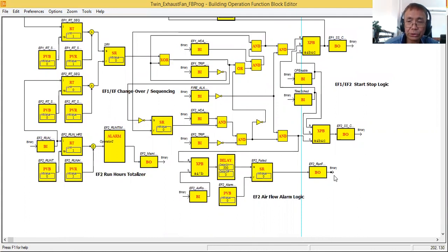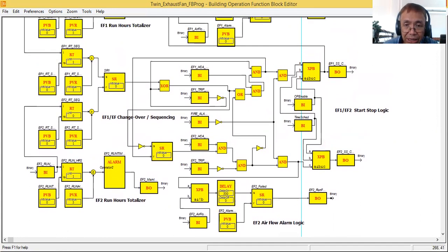So you will have three small programs that are easy to understand because they are small and manageable. But if you have a big logic, sometimes you feel you cannot follow the logic. So it's good advice to break your big and complicated control logic into smaller control logic programs which are manageable.